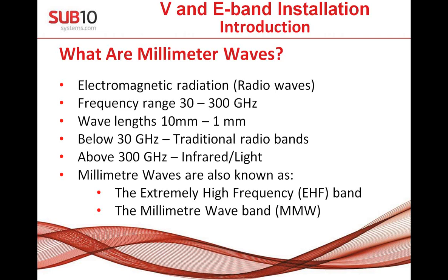The edge or border between traditional microwave systems and millimeter waves is not so precise, because currently we have a microwave system running at 38 gigahertz. What is key is really high-frequency systems or signals, typically starting from 60 gigahertz and higher. You can also see another abbreviation, extremely high frequency, and it's the same; it's again related to MMW, which is almost standard. Everybody says millimeter waves, and as I mentioned, it's from 60 up.